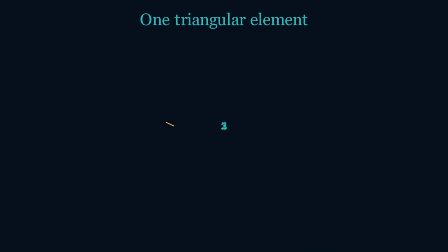The simplest 2D element is a triangle with three nodes, the constant strain triangle. In episode 2, each 1D node had a tent function. Here, each of the three corners gets one, 1, 2, 3, but now it's a surface. Watch the shape function for node 1. It rises to a height of 1 right at its own corner, and slopes down to 0 at the other two. A tent stretched over the triangle.